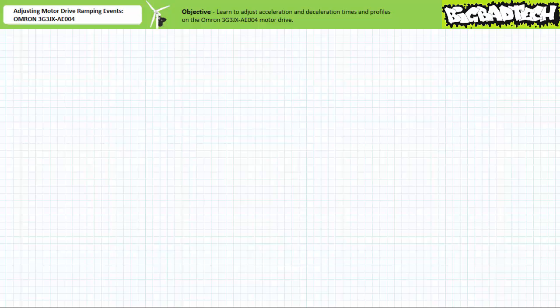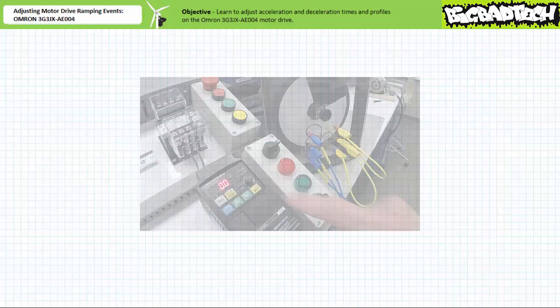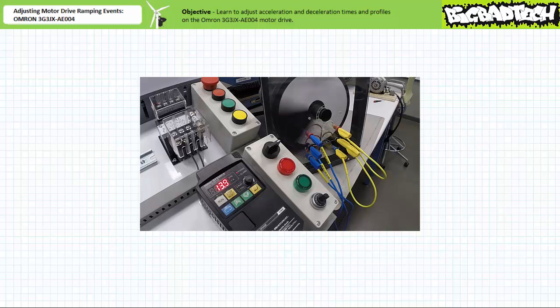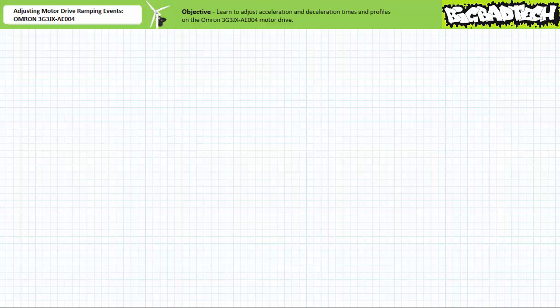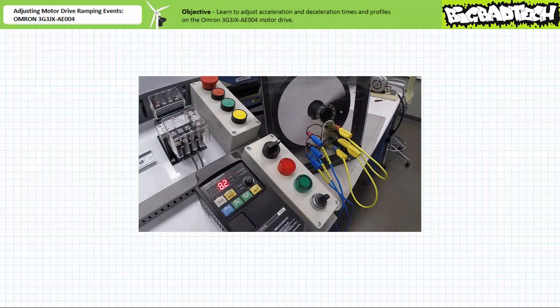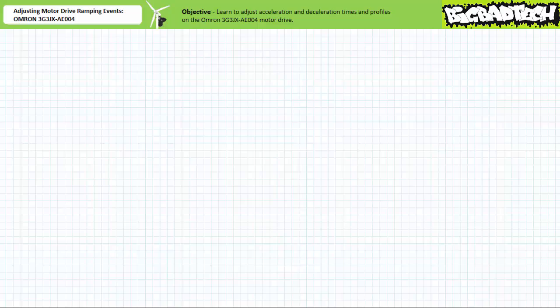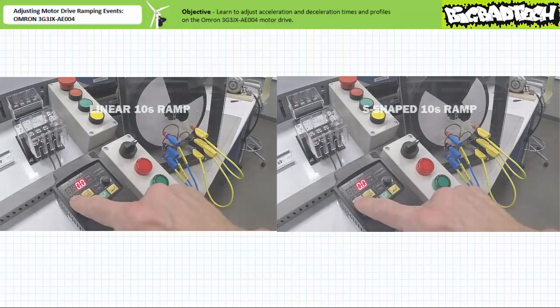It may help to compare the S-shaped 10-second acceleration with that of our initial linear 10-second acceleration to recognize the subtle differences between them. The linear 10-second ramp-up takes 10 seconds to linearly increase excitation frequency to 60 Hz. Whereas the S-shaped 10-second ramp-up starts off slow, then blows through a wide range, and backs off over the same 10-second period. As a result, for the iteration with the S-shaped curve, the motor and flywheel undergo an acceleration pattern similar to that experienced in an elevator traveling between floors. Here they are together.